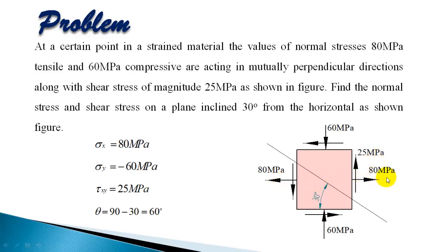Sigma x is positive 80 megapascal. Sigma y is negative because it's compressive, so it is minus 60 megapascal, and shear stress is positive 25 megapascal.